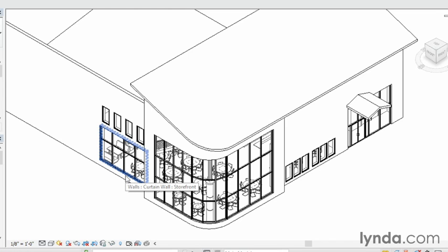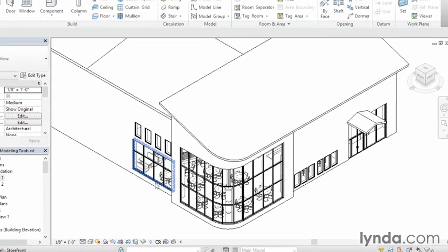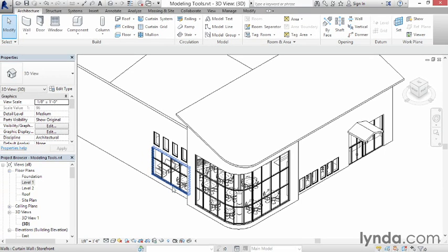Now, if you're having trouble getting it to highlight that dashed outer edge, you can press the tab key. And each time you tab, it will cycle through different options. And you can see there were several there. So there's the dashed edge, but each time I tab, you can see lots of other choices. That's called a curtain wall. Now, a curtain wall is just a more complex wall that's divided into parts and pieces. It is actually a wall.